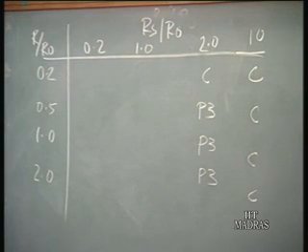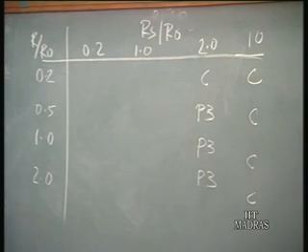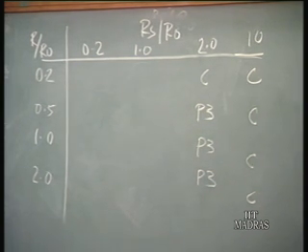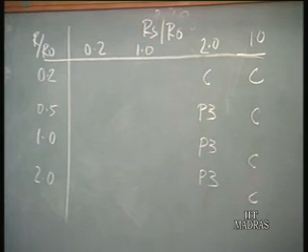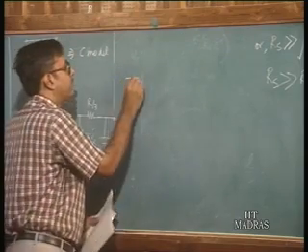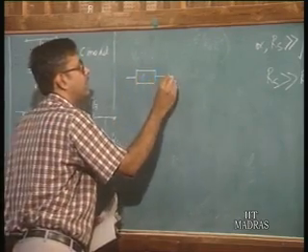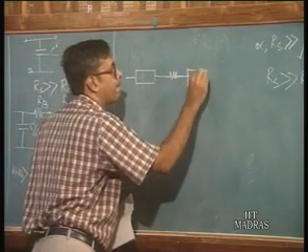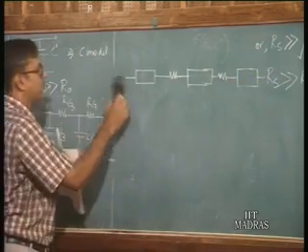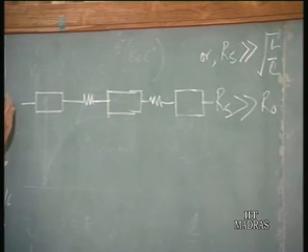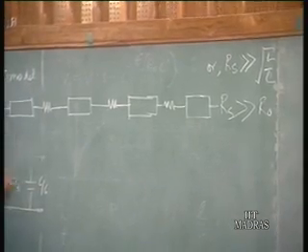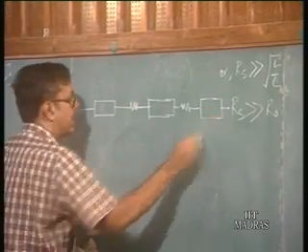So, for transmission line also we have two models. One is the normal one-section transmission line, which we have already seen. But when the resistance of the line becomes comparable, that is, it is a lossy transmission line, we have to go for what is called a 4-section transmission line model. That is basically a structure like this, with one more section here. So this is a 4-section transmission line model.